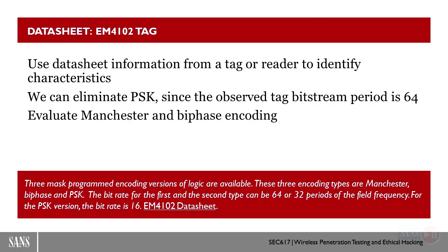So now what? We know that this might be an EM4102, so let's go look at the spec sheets for the EM4102. It tells us that the EM4102 tags can have some specific characteristics for their encoding so that we can potentially return that waveform back to bytes.